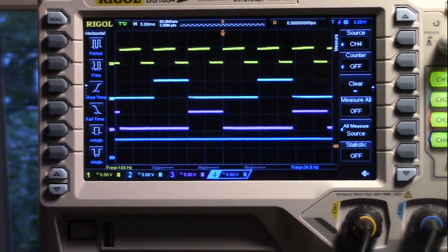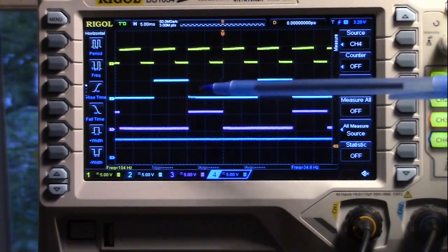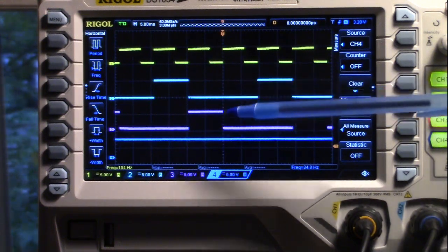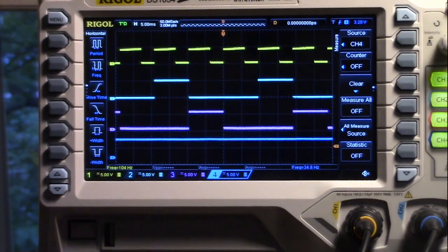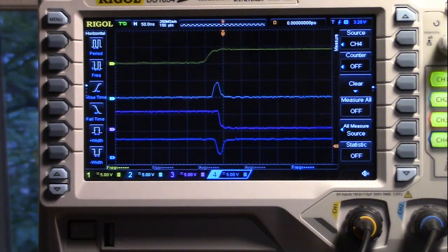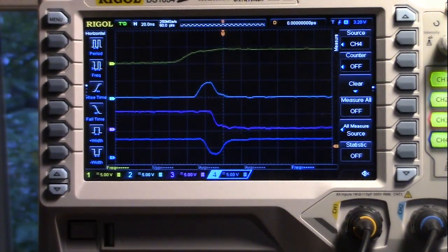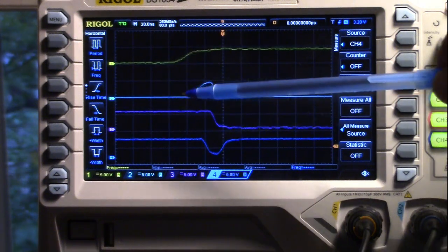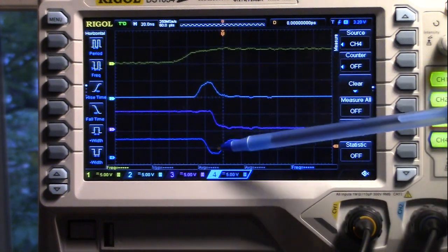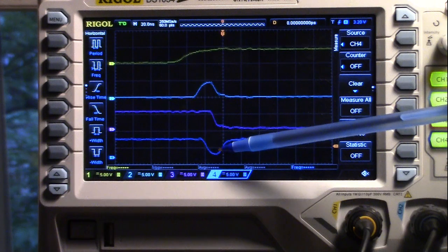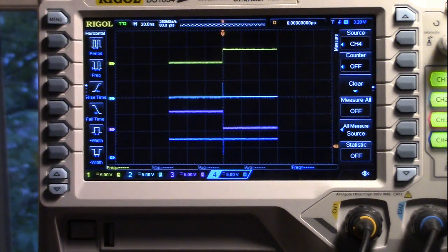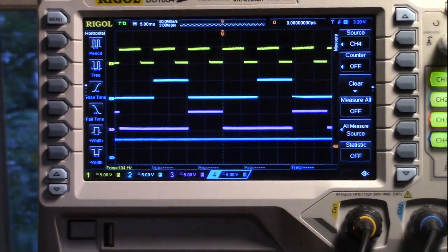We still have the problem that we are counting 0, 0, 0, 1, 1, 0, and then for a very short time here we are counting 1, 1. When we do that, we're getting a reset pulse, and once again we need to zoom in to see that, way in. And sure enough, when we zoom in to 20 nanoseconds per division, we see we've got the count of 1, 0, and then we go to 1, 1 for 20 nanoseconds. We NAND that together to get a low pulse, which causes the counter to clear, and we get an output 0, 0 in the counter. Once again, this is a very poor way to divide by n counters.